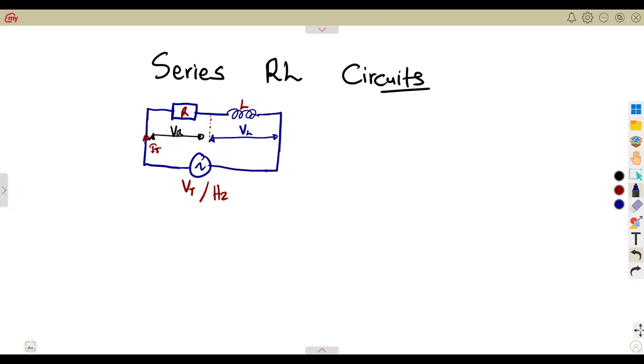So we understand that as we are dealing with AC theory, the sum of the voltages is referred to as the phasor sum whenever you're talking about this total voltage. All right, let's talk about this total voltage. The total voltage VT is not equal to the sum where you simply add VR and VL like what we had when dealing with DC circuits. No, this one is referred to as the phasor sum.